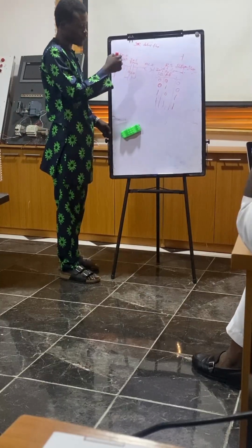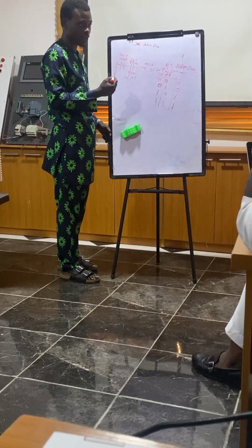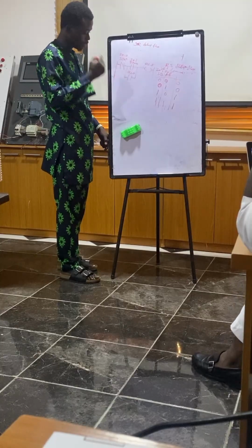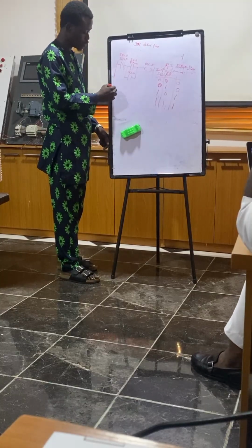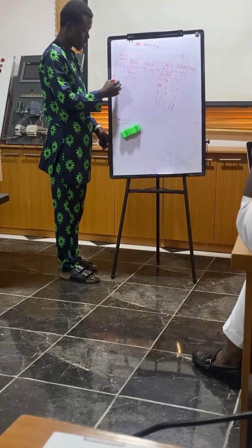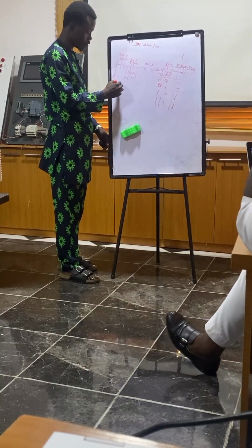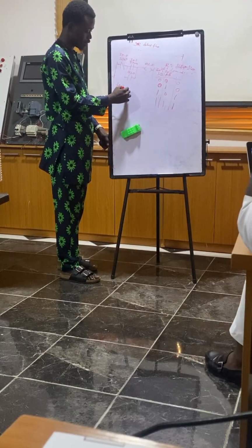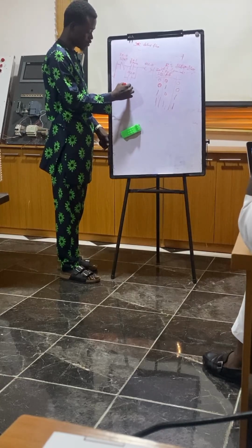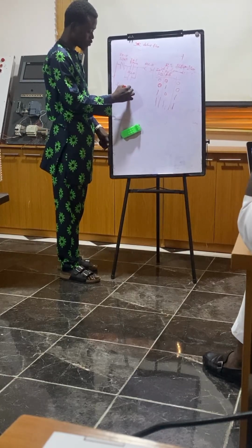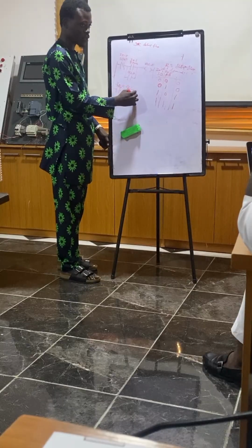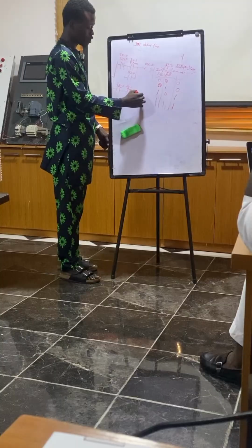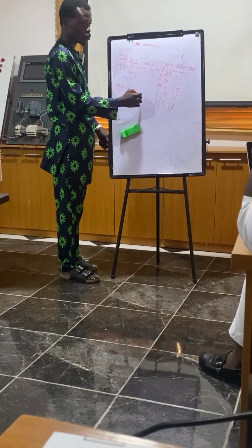Now, how do we infuse RS here? What's the condition for RS? The condition for RS is such that when the two buttons, I0.0, that is the stop, and I0.1, the start, are pressed, we still want the set to dominate.